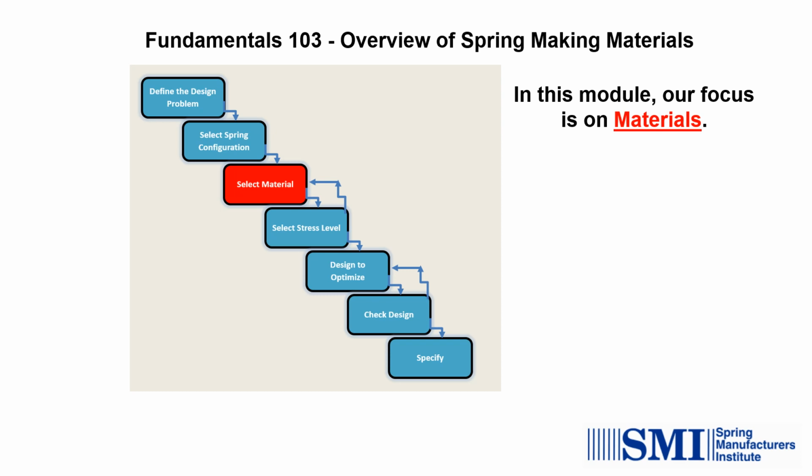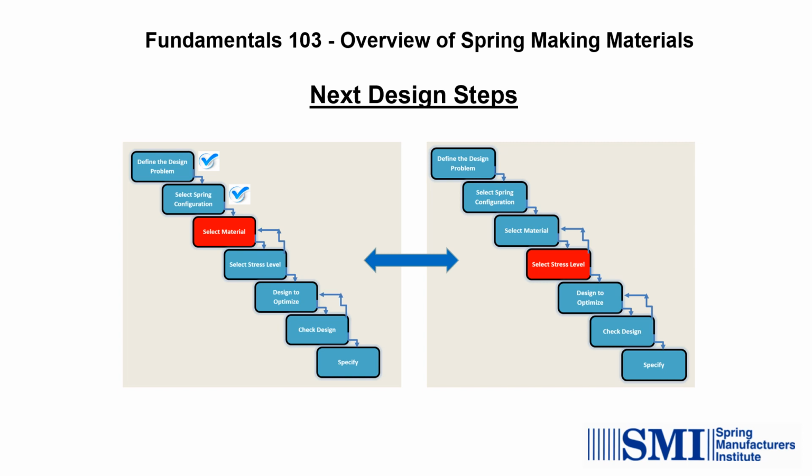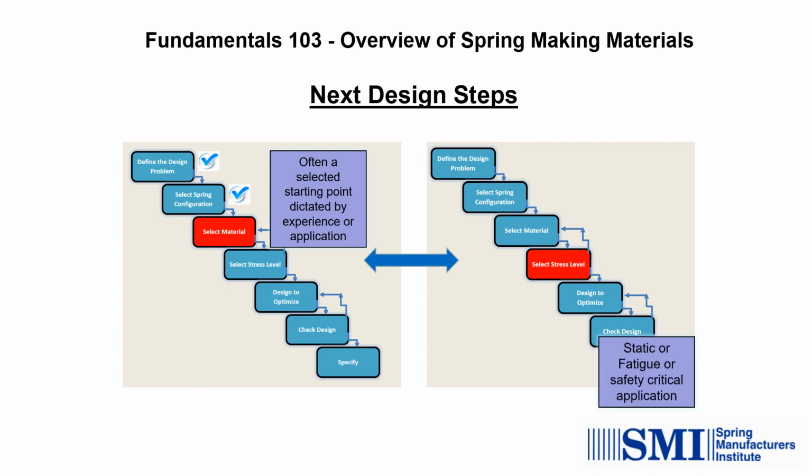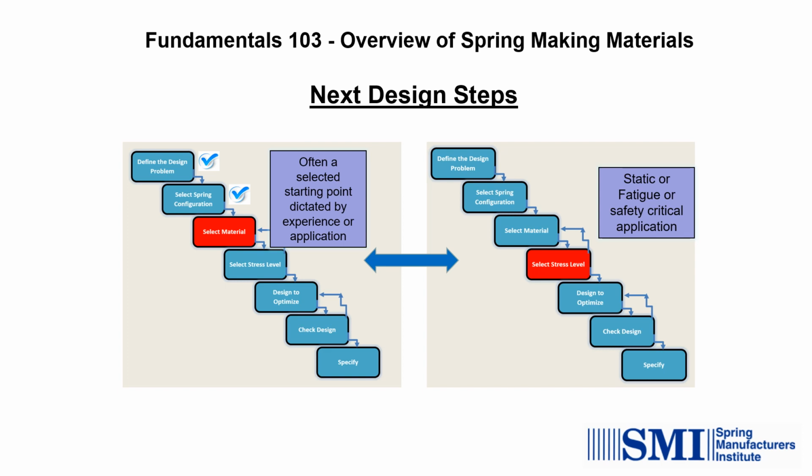In this module, our focus is on material. This slide emphasizes that material selection is often dictated by experience or the particular application. With regards to selecting the stress level, it is important to know if the spring will operate in a static or dynamic condition. Is it prone to fatigue, or is it a safety critical application?